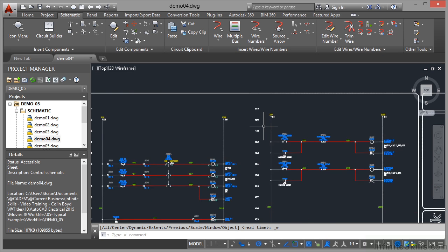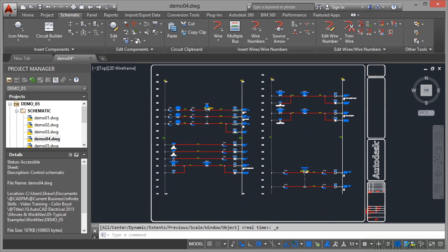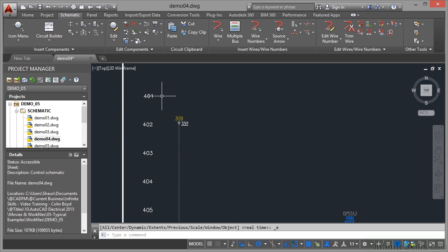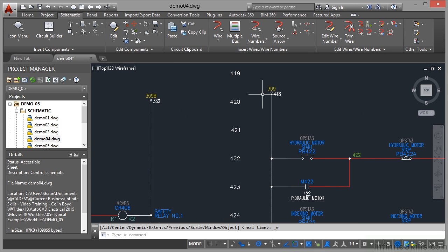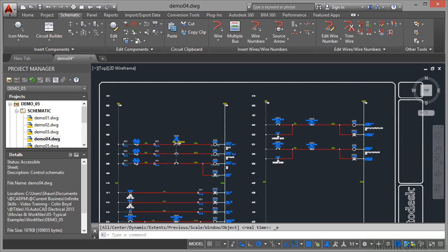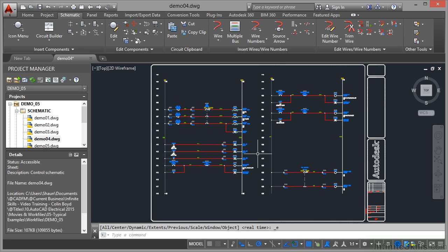So what you can do is you can split the ladders as well and number them accordingly. So I put one ladder in there and tell it to number from 401 right there, and then this one I'll tell it to start at 419. So it allows you to obviously work with these tools such as logic ladders by placing the components going across from one side of the ladder to the other as rungs. And the good thing is each rung is numbered.